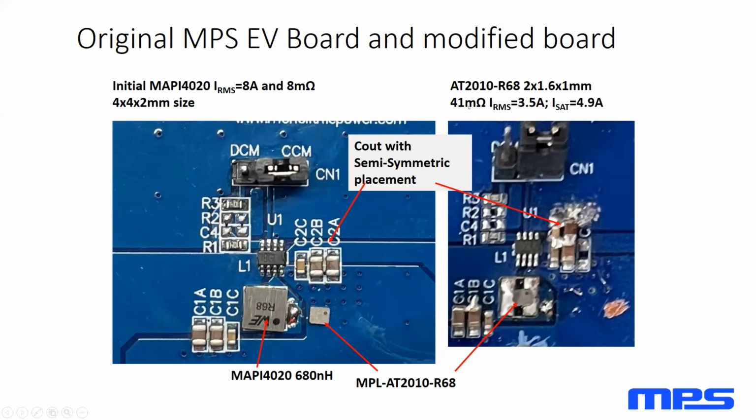So this is a 2x2, 1 millimeter high inductor. Obviously, with the smaller size, there is going to be some trade-off. This particular boost, I think the peak current limit is only about 1 amp, so it's not going to be providing tons of current. So this is probably overkill, but the DCR is pretty good. We're getting a little bit higher DCR, a little bit lower saturation current or RMS for the temperature rise, but this was the idea. Let's change this and see what we can do.